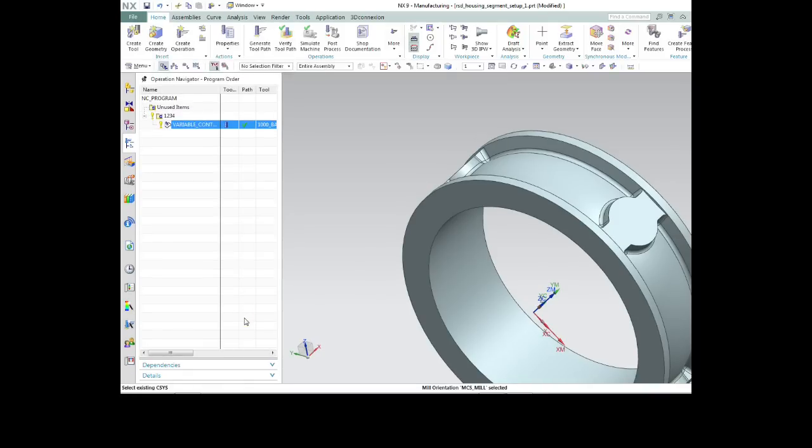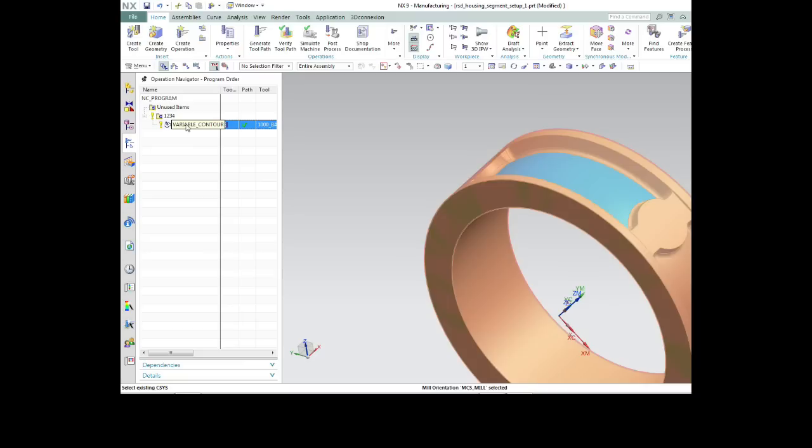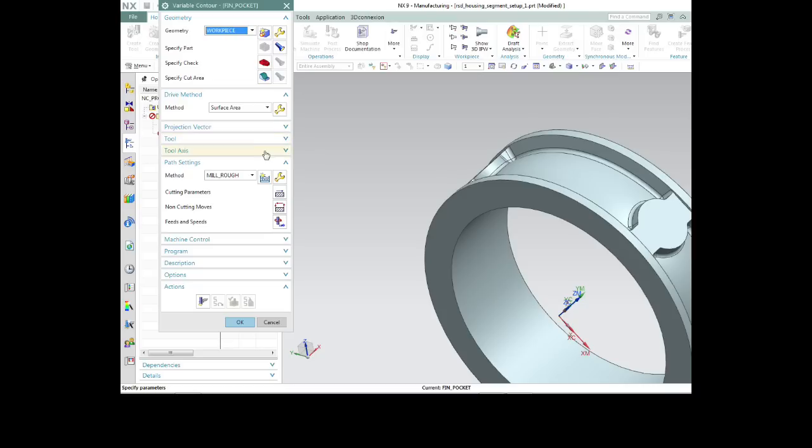I'm going to say OK to this and save the cutter path. Now I think we'll rename this. We'll call this rough pocket. And we're going to copy that. We're going to paste it. We'll call this finish pocket. And so all we have to do is go in here and edit.